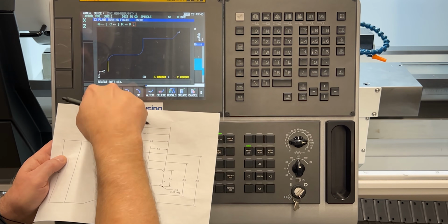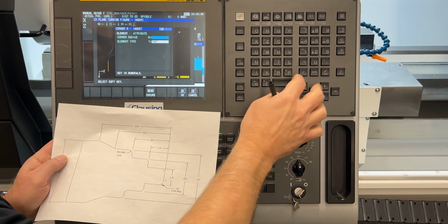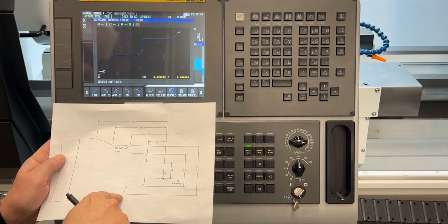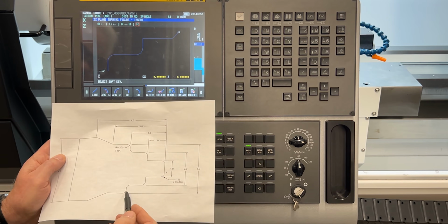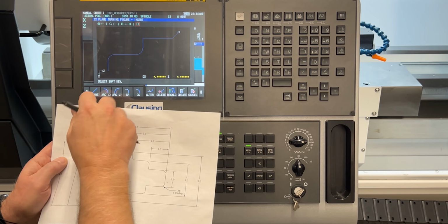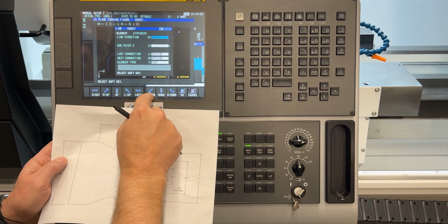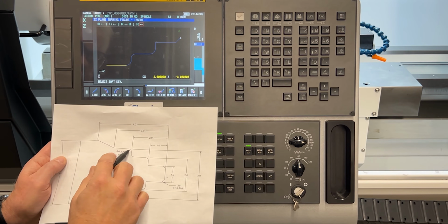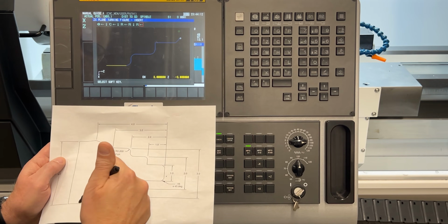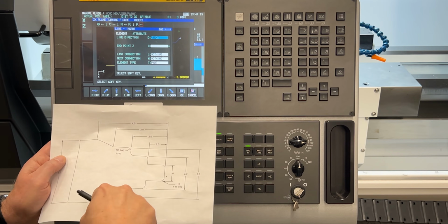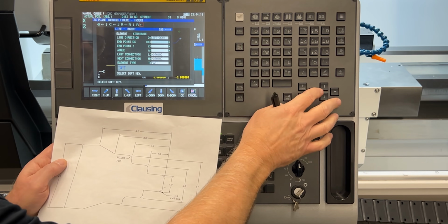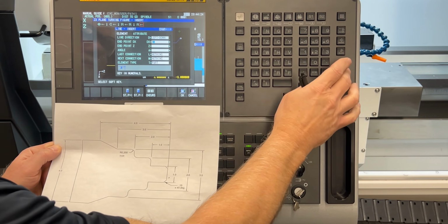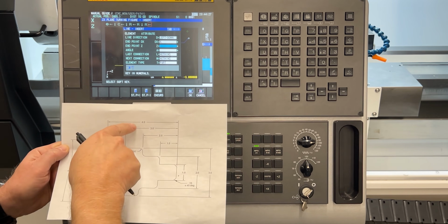At the end of this move, I'm going to do another radius blend and put in there 0.2. OK, still doesn't show it until it sees the next move. Next move is going to go from here all the way back to Z minus 3, the line to left, Z -3. OK. So we have that line in there. We're going to do another line. And this time we're going to actually do a left down. So X is going out to 4-inch diameter, and Z is going to be a -4.